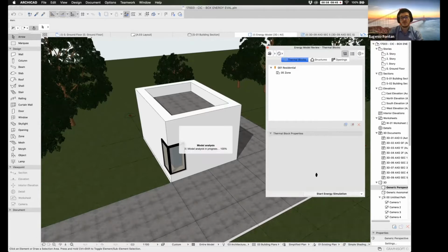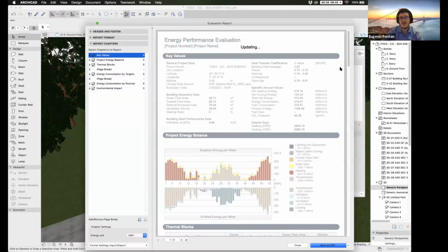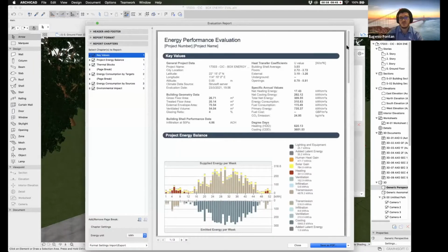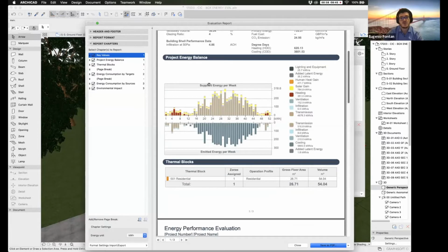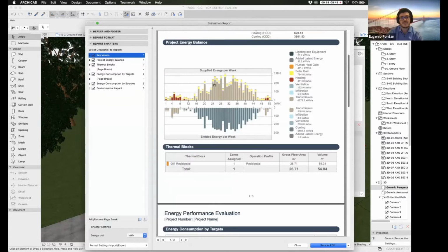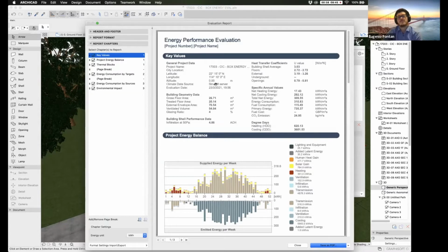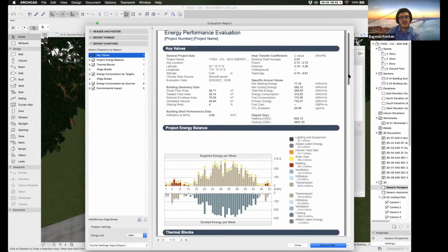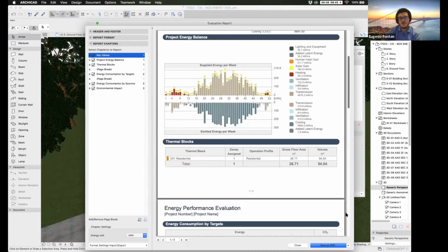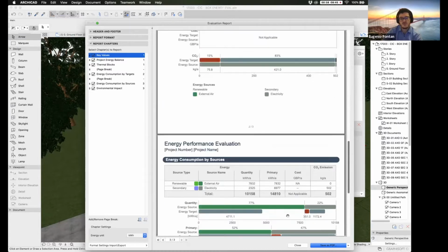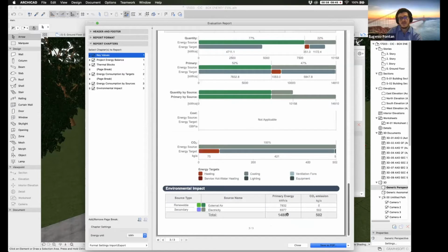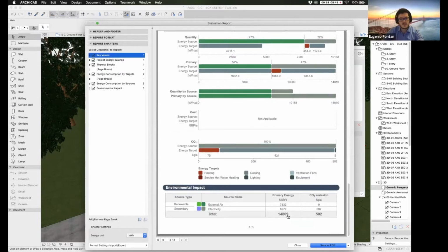So the same box, if it's located in Hong Kong, look what happened. If we go to the values, first of all, you can see here that it doesn't say the same climate data source. It used to say Madrid, Spain. Now it says somewhere else, which is probably the server where it gets the climate data. But also let's go down here and look at this. The primary energy, the total energy we were using, I think it was like 23,000 kilowatts.